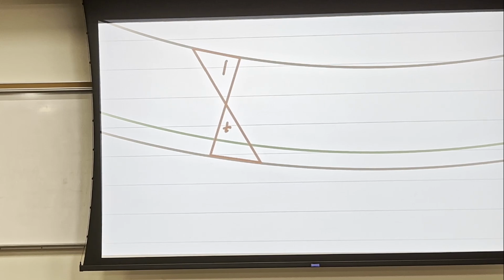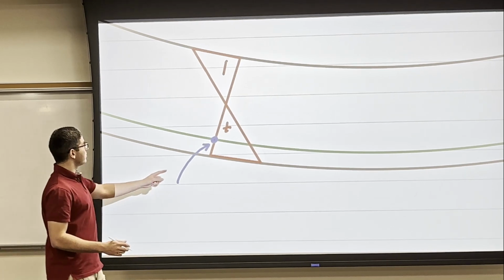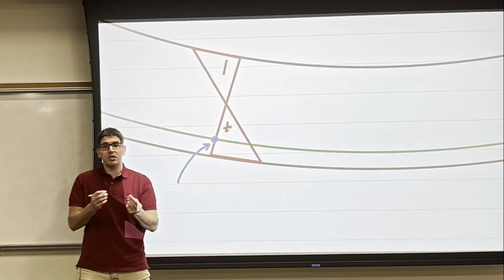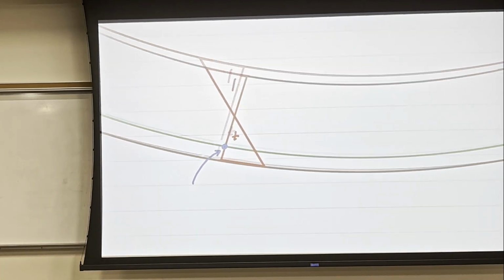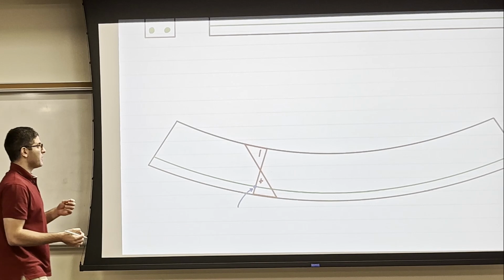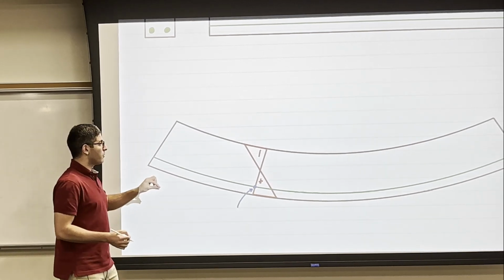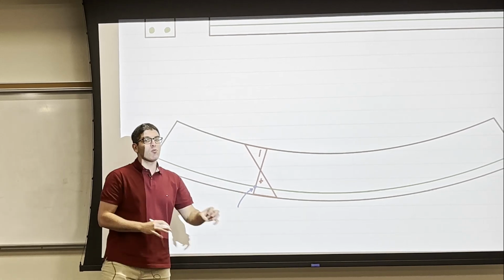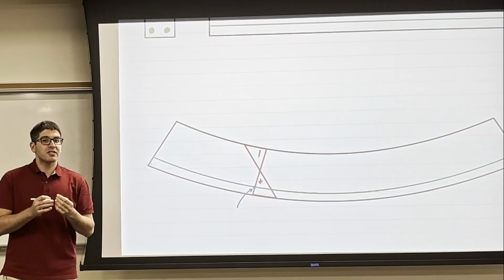But at the interface between the steel rebar and the concrete, they have the same strain. You don't see any drops. Because if you saw a drop, that would mean the steel is deforming differently than the beam, and you would see the steel popping out. For the beam to work together, they need to have the same strain.